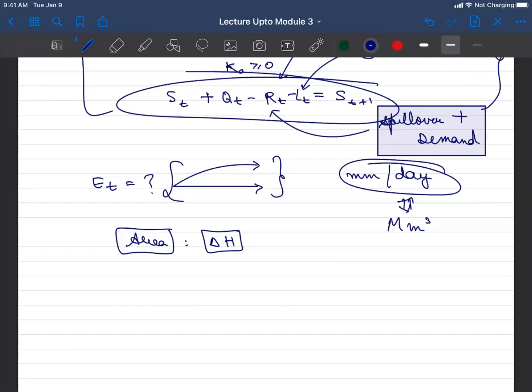It would be just a rounding error if you look from the dam height perspective. But what is the area of a dam? I told you about the backwater of Bhakra Dam. It goes all the way to 90 kilometers. So it's a big issue of scale. What we typically ignore as a rounding error in other fields becomes a big quantity for us, which we cannot just overlook. So that means just using gauges to measure evaporation would not work.